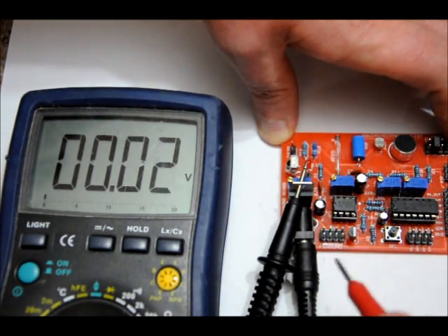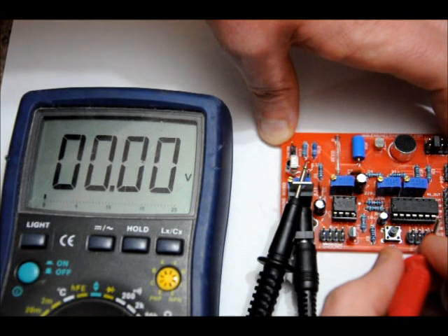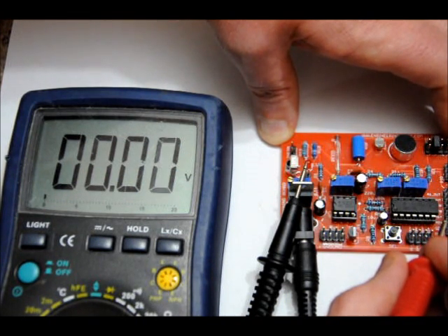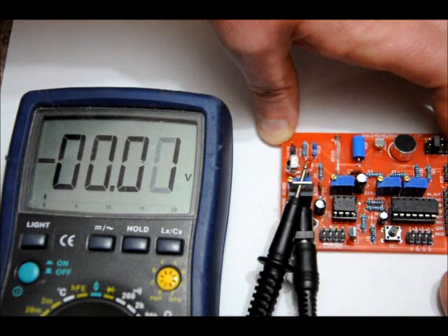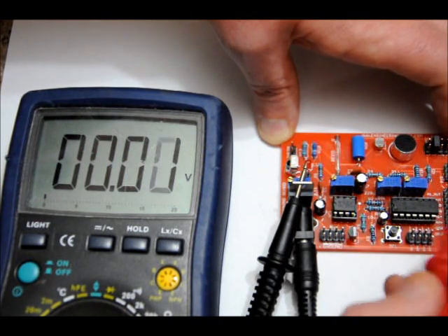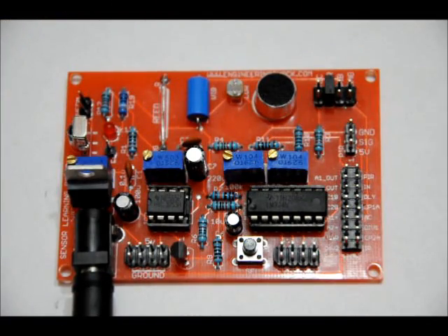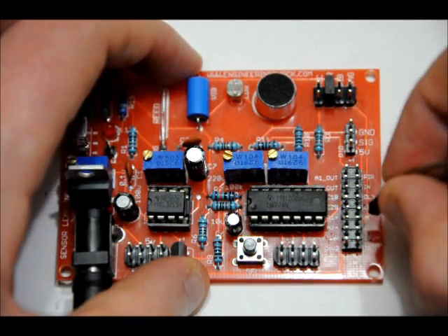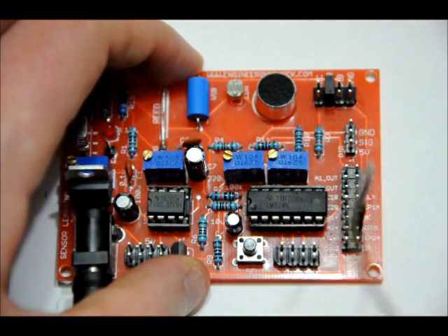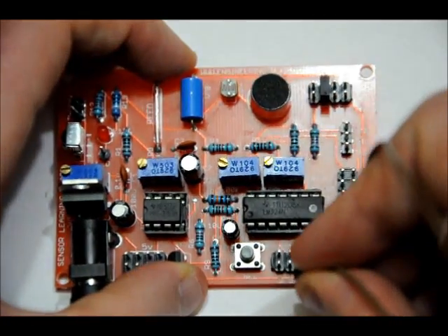So in any case, we're going to follow the plan. We're going to tune our variable resistor to output 3 volts, and then we're going to make our connections. So stop the video, tune your VAR pin to 3 volts, and then we'll make the connections to our comparator. So step number 1, we're going to take our div 1 pin from the light sensor circuit and connect that to the C1- pin on the comparator pin block on the bottom. So div 1 to C1-.